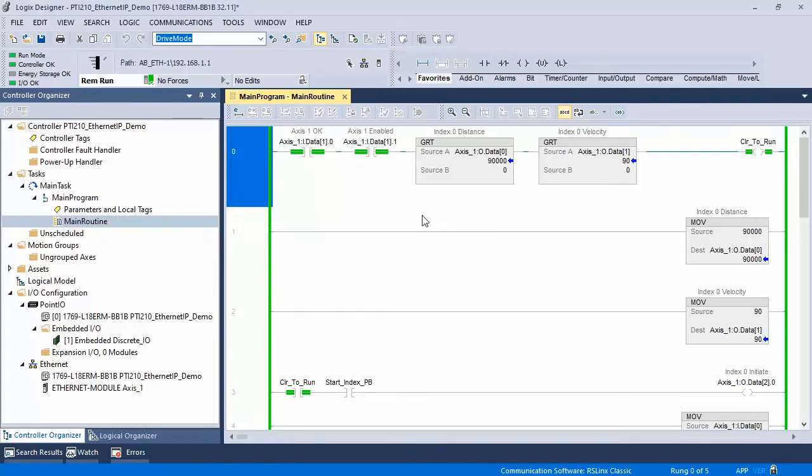And if I were to go look, even PowerTools Pro would show that there is distance and velocity. But until you actually update the tags using the field bus, in this case Ethernet IP, you won't have distance or velocity in my case. I'm going to show you PowerTools Studio here in a minute.